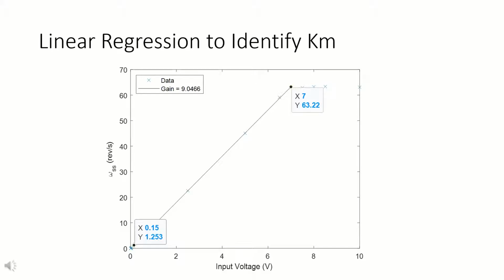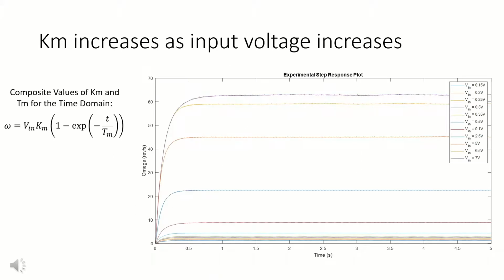This experimental plot shows the step response in the time domain for all Vn values in the linear range of the data. Km increases slightly throughout the linear range. Tm has minor fluctuations throughout the range but remains fairly constant. This reveals that the model is not 100% precise. Uncertainty within the measuring devices could be a contributing factor for the varying Km and Tm values.